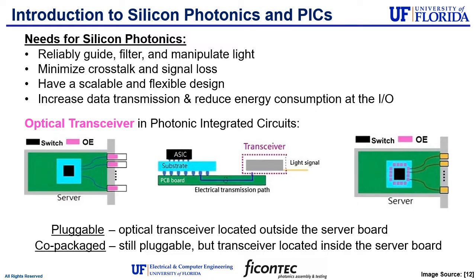So a device that bridges the gap, being the optical transceiver, was invented to facilitate the connection for photonic integrated circuits, or PICs. Now, initially, optical transceivers were these pluggable modules soldered onto a PCB and connected to a server's logic. But advances in photonic integrated circuits now enable these co-packaged solutions, placing transceivers inside logic substrates to maximize performance. Now, placing these transceiver modules as close as possible to logic maximizes the benefits from using photons and is enabling extremely fast data transmission speeds.